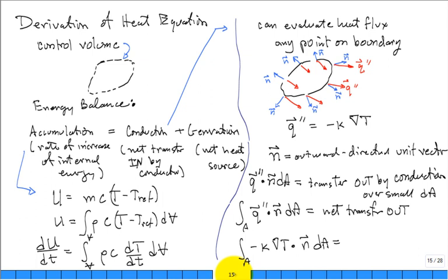So what I'm going to do in 2 slides is derive the heat diffusion equation. It's an energy balance statement. That's how you derive this equation. So we start off, and we have our coordinate system, and the volume of interest is out there, and we select a portion of it. We identify that portion by a control volume. That control volume has an interior, like you would expect, and a well-defined boundary that encloses that interior.